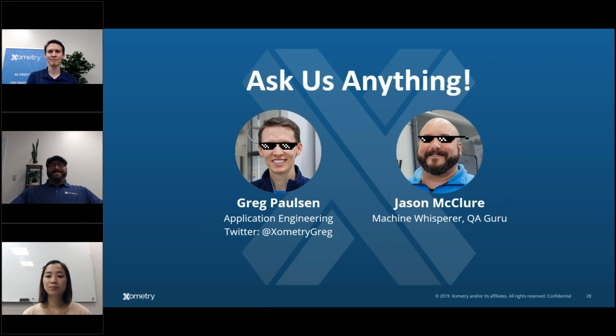Great. So can you do a flatness callout on the datum plane? Yes, absolutely. That's probably the preferred spot. Flatness is non-datum just because it's saying this plane, it doesn't refer to anything else. It's just saying this face, what's the deviation of it? But you can definitely add flatness to a datum plane, and honestly, it's pretty common because usually you're measuring off of that anyway, so you want it to be to a certain level of flatness. Quick and easy. I like it.